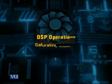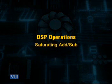Now let me talk about these issues one by one in detail. The saturating add subtract is very, very important, because DSP results cannot ignore the overflow conditions. If we ignore the overflow conditions, then there are chances that we may miss certain events which are to be taken care of.